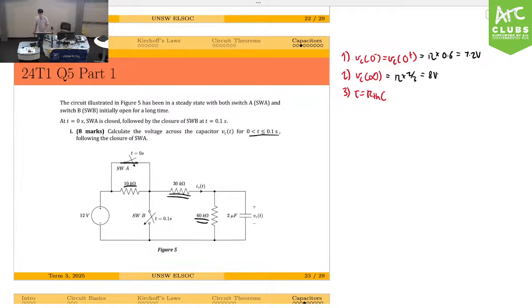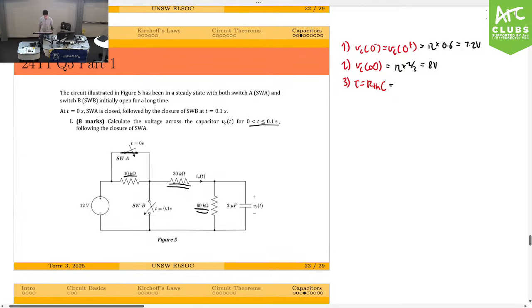All right. So we've got those two parts pretty quickly. Maybe I should be more clear in what I'm saying. When I'm finding these two, I'm assuming that our capacitor was at steady state. So really, these are open circuits, so you don't have to consider that. Or you're measuring the voltage across it at steady state. OK, so that's those two.